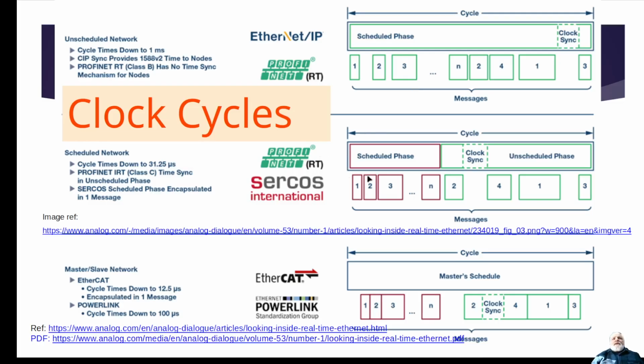Now SERCOS is kind of the same thing. It sends a clock signal here, but it provides for a scheduled phase and then an unscheduled phase. The idea is you have your speed for your robots coming every millisecond or whatever, but it also saves some time to send some data that is not repetitive, coming every so often.